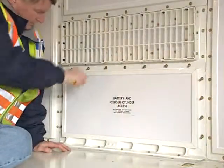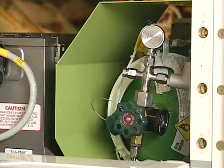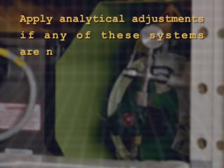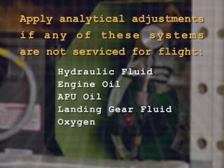Also, check to ensure all oxygen bottles are serviced for flight. Note, if you cannot service any of these systems for flight, you must analytically account for the weight and CG effects produced by any missing fluids.